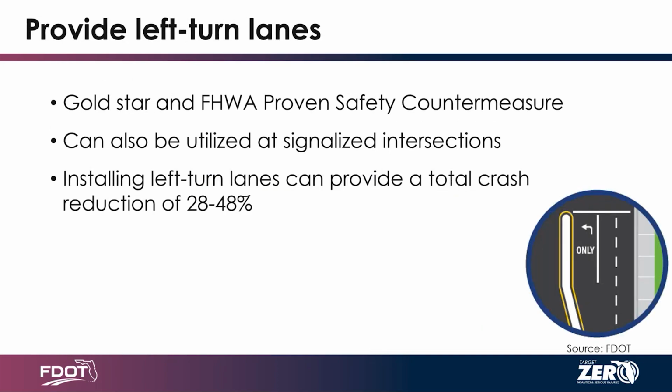No, so when we're talking about unsignalized intersections, I'll just say generally throughout this module, we're referring to two-way stop controlled. And so the state road would be free flowing, and then the minor street, potentially a local road, would be stop controlled.